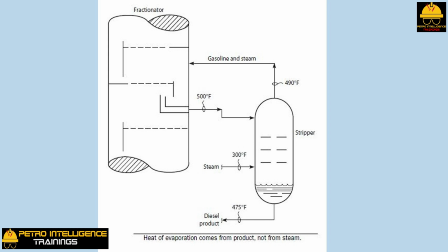I was once working in a refinery that could not meet the flashpoint specification for its diesel product. Flashpoint is the temperature at which a hydrocarbon will ignite when exposed to an open flame. To raise the flash point of diesel oil, it is steam stripped to remove the lighter, more combustible components. I noticed that I could drain water from the bottom of the steam supply line to the diesel oil stripper.